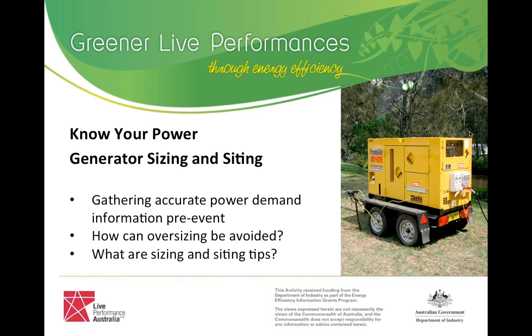Okay. But we can measure that for you in terms of what's the difference in fuel consumption rate from say 100 to 150 kVA, and over a 4-day event that could be significant. Okay, so there's a real lesson to be learned there. It's like hiring a car. You're hiring a V8 or you're hiring a 1.3 litre car.